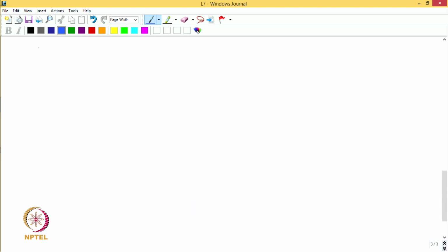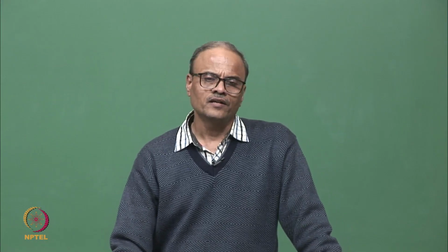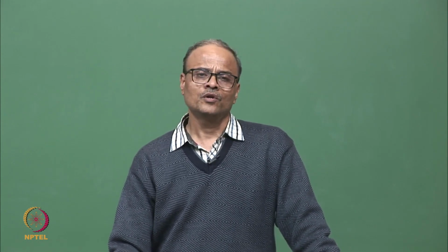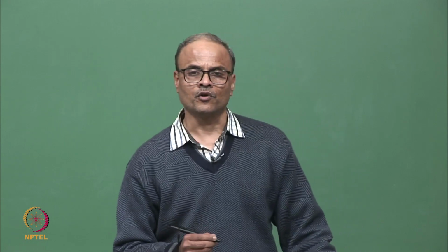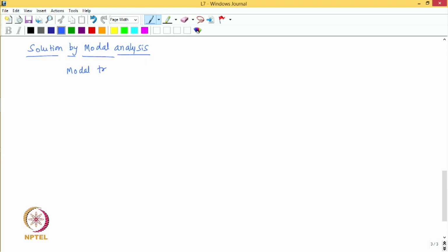Now, we are going to solve the equations by the procedure of modal analysis. Solution by modal analysis. In this procedure, what is done is that instead of solving the differential equations directly in the coordinate x, we first transform the equation to modal coordinates. So, let us try to see what this transformation to modal coordinates means. Let us see what is meant by modal transformation.